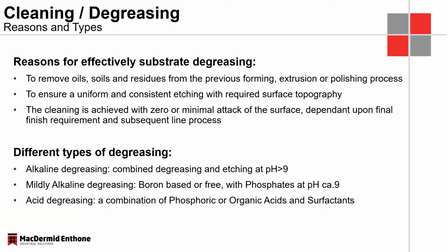I think the most commonly used cleaner for aluminum are the multi-alkaline degreasers, and these are based around about a pH of 9, and they hardly have any attack on the surface. So they're very well pH buffered, they're inhibited, and we see immersion times of up to half an hour, a few hours without any attack on the surface.